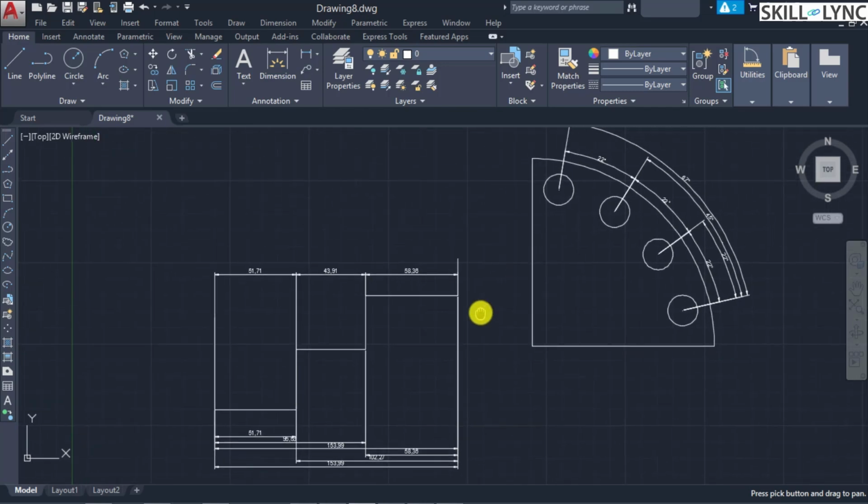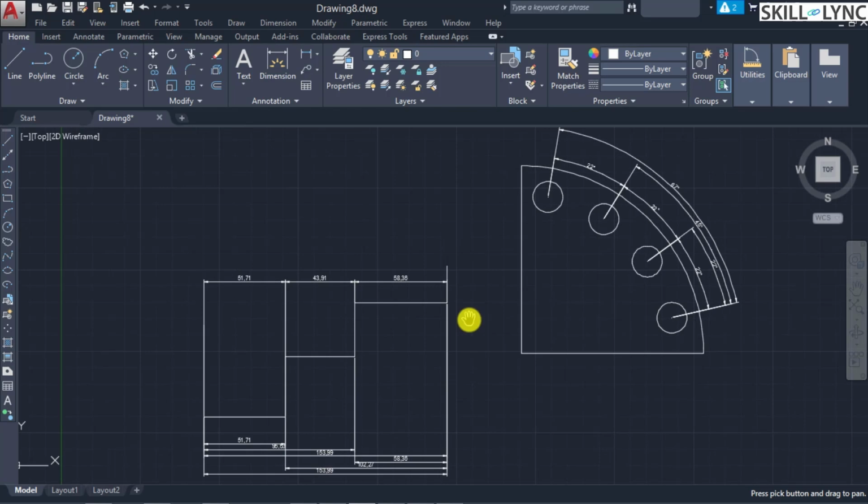So this is how differentiating between a baseline and a dimension continue modifies the pretext of measuring the feature at the end of the line. So you need to be very careful of how you give out the dimension. It's not about ease, but rather how to measure it at the end of line or during inspection.